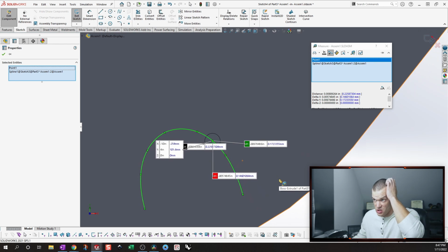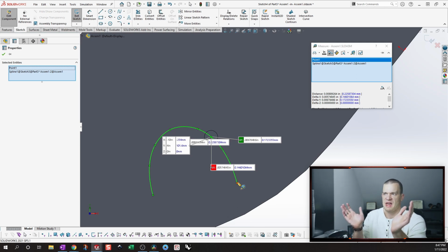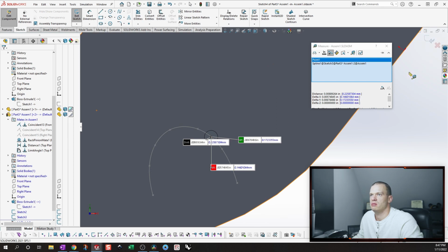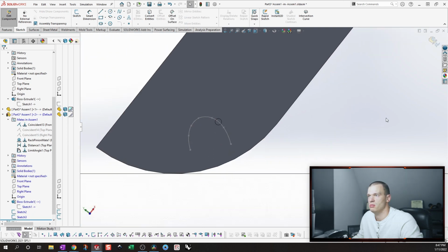Seeing how that's a giant pin that sits into a slot, and you're really only concerned with the endpoint conditions because the pin will be free floating inside of that slot during motion. You don't want it stopping anything. It's only a hard stop at the end of its track. Within 8 thousandths is pretty good. You're going to have tolerance in there anyways so that it doesn't bind. So it's pretty good for just using SolidWorks as the hammer to do your math calculations.